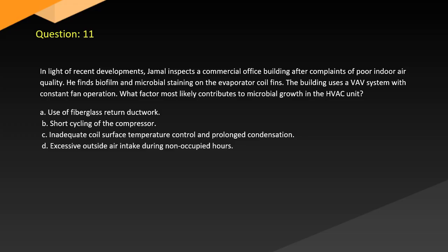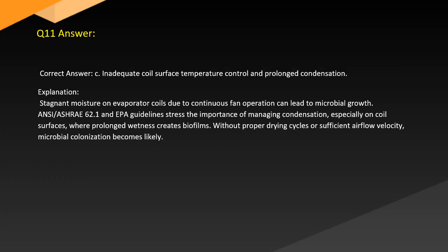A. Use of fiberglass return ductwork. B. Short cycling of the compressor. C. Inadequate coil surface temperature control and prolonged condensation. D. Excessive outside air intake during non-occupied hours. Answer. Correct answer. C. Inadequate coil surface temperature control and prolonged condensation.